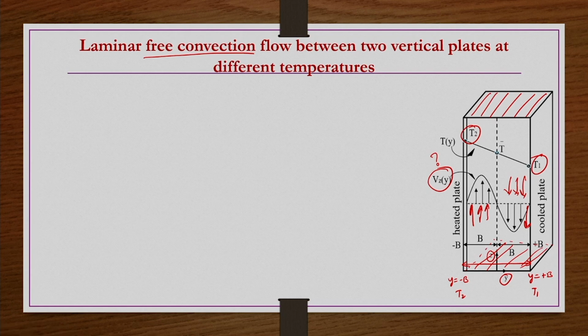Now, for this case, how is Vz changing? If it is isothermal condition, then we can solve by simply simplifying the continuity and momentum equations, and one of the momentum equations would give an expression for tau yz. For the given fluid nature, power law, Newtonian or Bingham plastic, you substitute, integrate, apply the boundary conditions, and get the velocity profile.